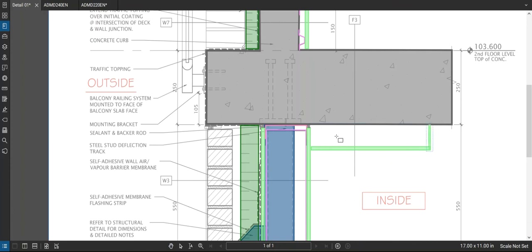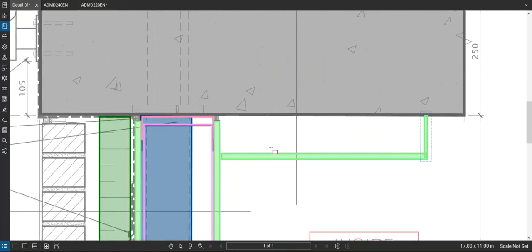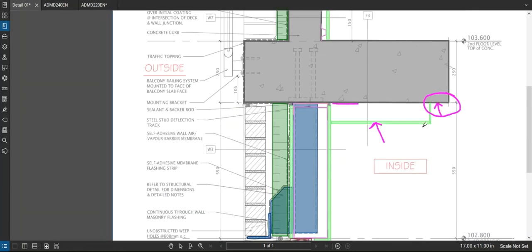It wouldn't do you much good to put metal studs in there, but you could frame it down with, say, some wood, and then fill that with spray foam, because the spray foam would act as a vapor barrier, and it would prevent any warm, moist air from ever touching that cold surface. Usually about 300 will do it.